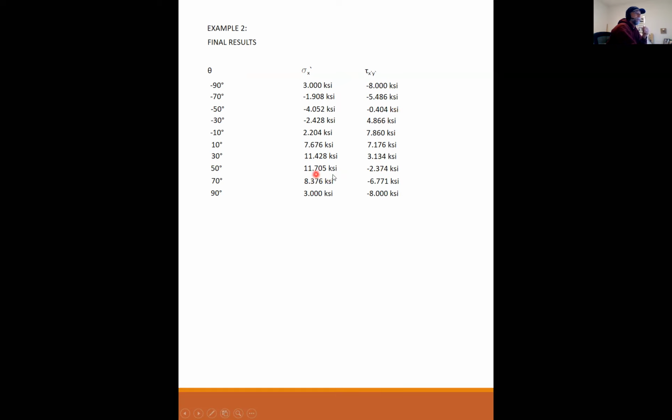You don't see it here because we didn't hit the maximum right on the nose, but somewhere between these 2 points, the shearing stress is 0, and somewhere between these 2 points, the shearing stress is 0. So where you hit your principal stresses, at exactly the same point, you hit your 0 points of shearing stress.